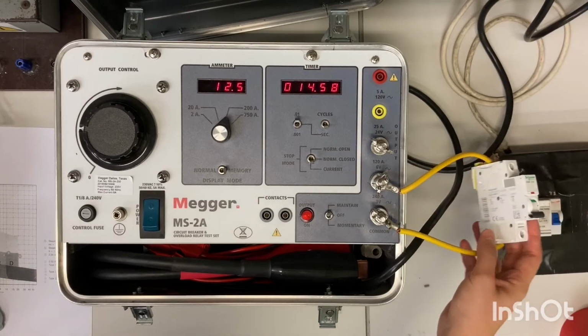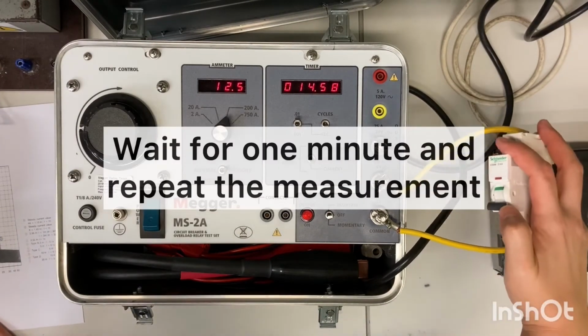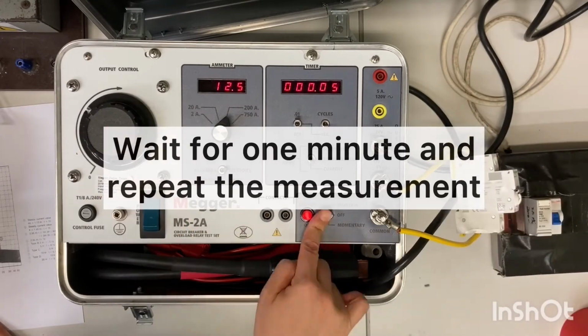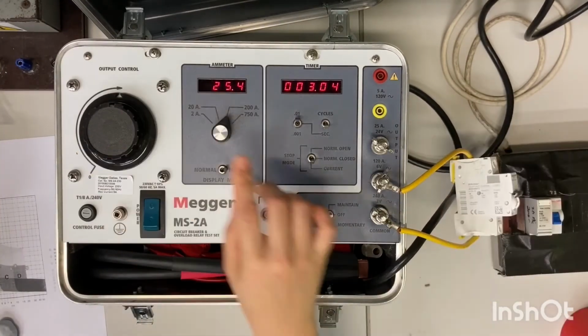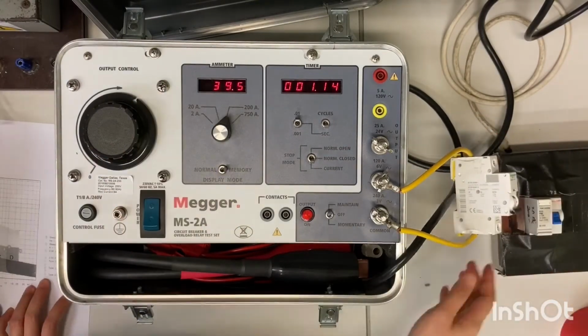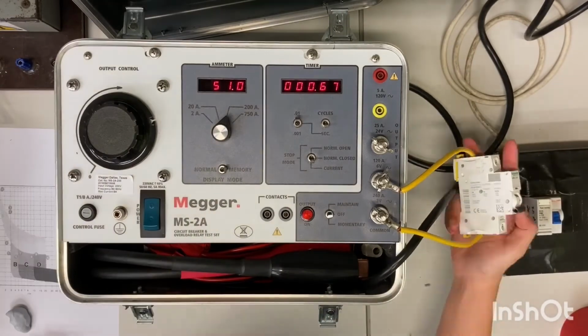We heard the click sound and the MCB has just tripped. So once again, record down the data and wait for 1 minute for another measurement. And we repeat the above procedures for larger current values until the MCB trips instantaneously.